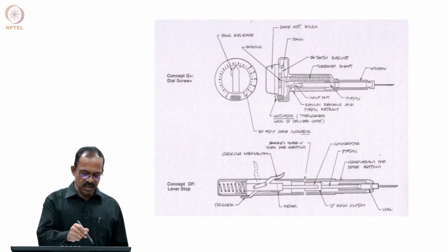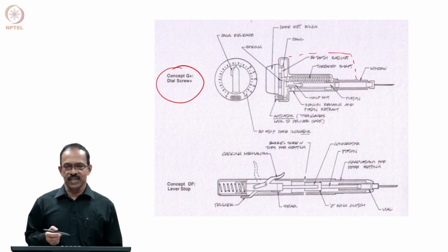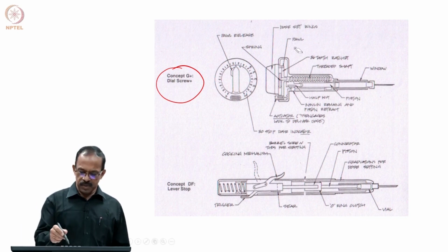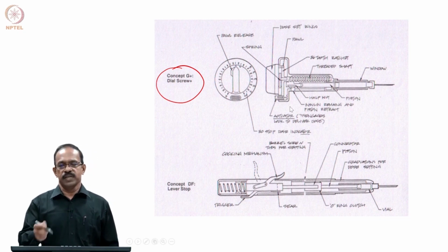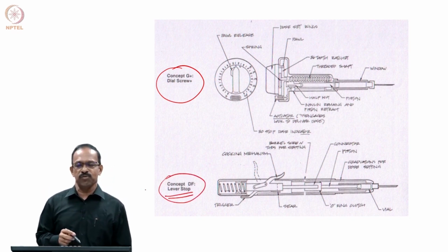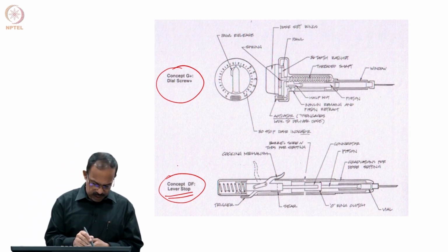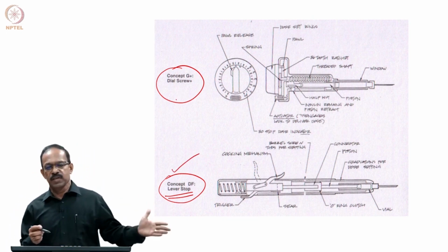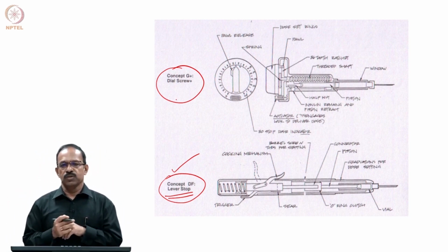So, if you do this, you can see that G plus, the original G was actually a bulky one, it was something like this. Now, by improving the design and addressing the bulkiness issue, it has become smaller and the bulkiness has gone, and therefore the ease of handling and portability improves. And then combining the D and F, D had some good features and F also had some good features. So, try to combine these 2 good features and come up with a new product, concept DF. Now, we take these 2 plus the previous 1, 2, 3 rank and take it to the next level, that is the concept scoring.